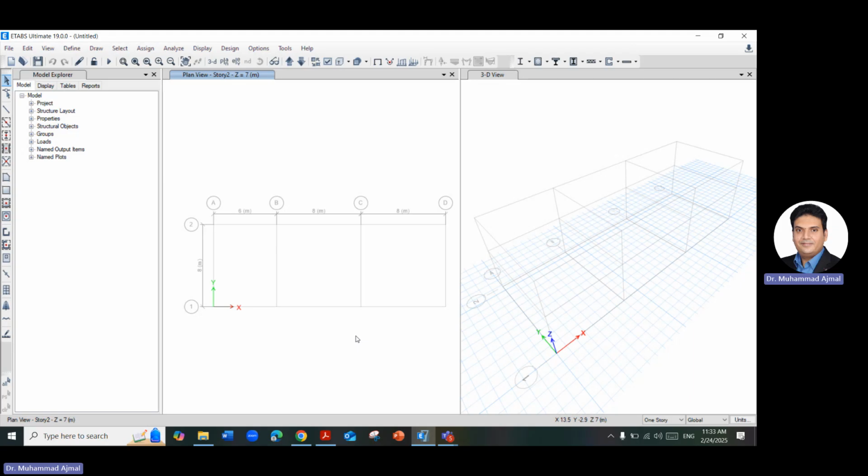Now, modeling, usually we don't go into this place. We model everything in the elevation. You assign beams, columns, then move to the next elevation, you assign beams, columns, and automatically it appears in the 3D view. Now, in our case, we have a beam. I can model it at this location, or I can model it at this location, because this is just a reference grid line. Because there is no beam, it is like an AutoCAD reference place, and you can just go and model there.